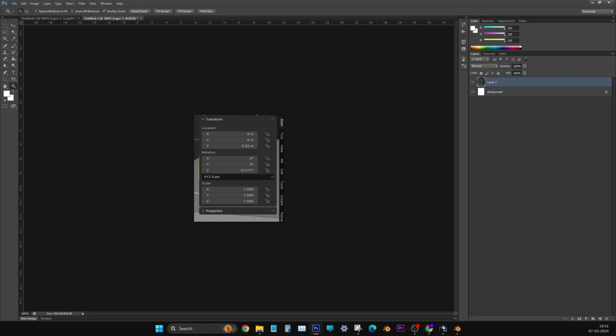Press 7 in the keyboard and then go to top view. Now using this left hand axis, just move it leftwards along this x-axis line. Not much, only one square. That little gray color line is there, no? There you can stop. A little more. Enough. Now you have done it.